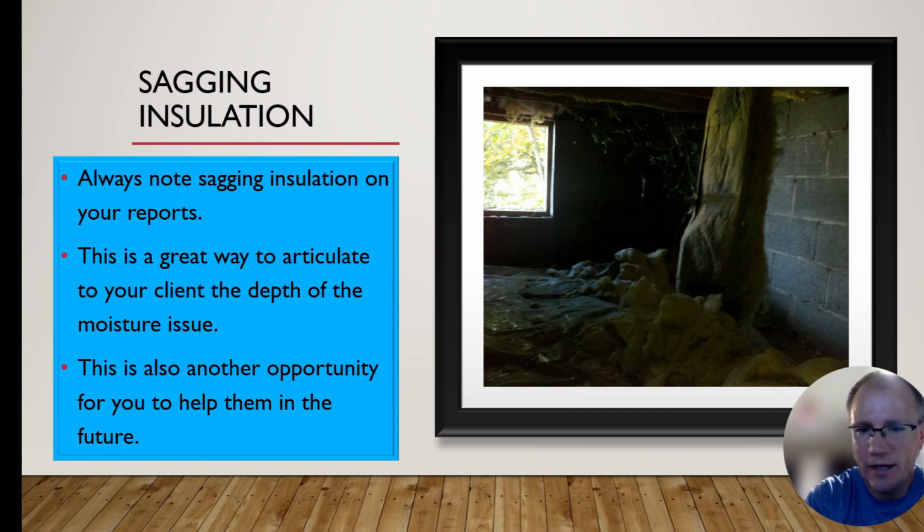So imagine if somebody came out of your crawl space and showed you a photo like this. You would definitely understand that there must be condensation or something rising up to your floor joist and causing your insulation to sag down. As that moisture lifts, that condensation is making that insulation really heavy and making it sag down. So again, this is something you need to note, because as you're looking at crawl spaces and debris, this is something you definitely can't leave on the floor. You wouldn't be able to do any work in the future with all that insulation on the floor. This is another opportunity for you to help your client with something that is going to be a major issue in the future and already is now.